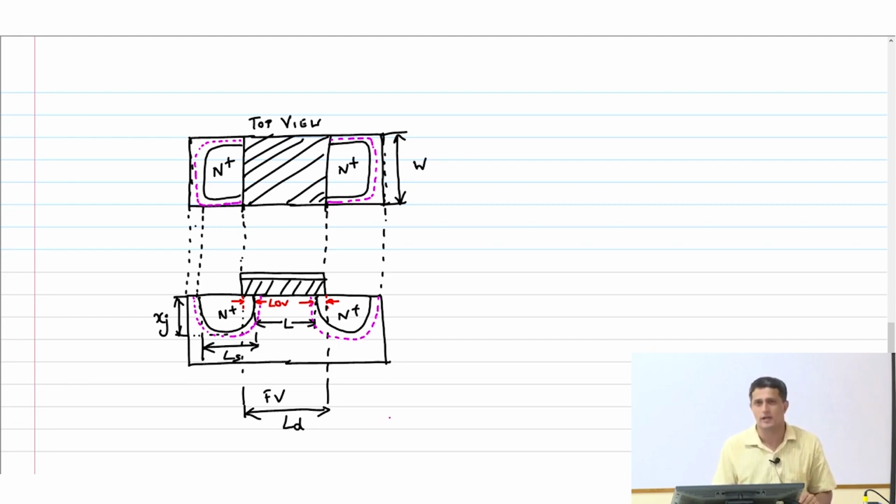gate voltage, that depletion region just seamlessly merges with the depletion region under the channel. So therefore we don't consider that fourth side when we are taking into account the calculations for capacitance here. That fourth side is basically accounted for under the gate, because we have already considered the gate capacitance and other things there. So we don't want to double count that here. This is just one convention, by the way. I am just giving you the rationale behind this kind of convention.